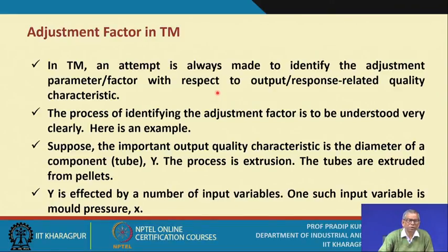The effect of external as well as internal noise factors. Once the product has been designed in such a way that the effect of internal as well as external, uncontrollable noise factors is minimum on the performance of the product, then you say it is a robust product, and the design methodology which you apply to create such a condition is referred to as the robust design.